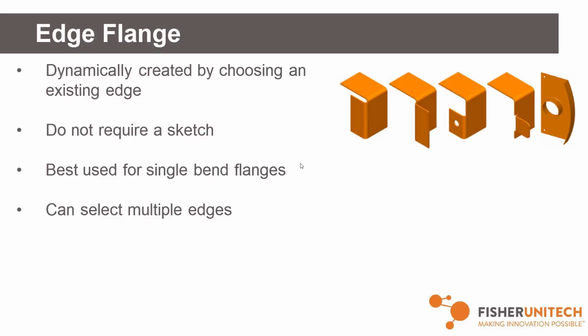This is just pulling additional material off of wherever your base flange starts or whatever your beginning sheet metal piece begins. And then you're adding on material to the sides. The bends are automatically being added. That's why in the beginning we set all of those K-factor values, all of those other bend values. And we'll get into some more of this stuff when we actually get inside the software, so it makes more sense. This is just so as we're going through these steps, you're like, oh yeah, okay, you already talked about that.